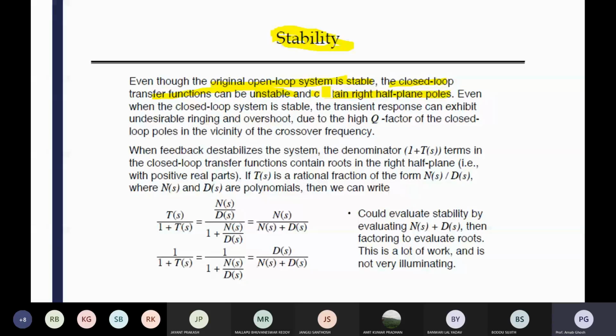If one root of the denominator is in your right half plane, you can say that it is an example of a non-minimum phase, which has some other problems that I discussed in my previous slides. There is no such direct effect on your magnitude, but there is an effect on your phase.